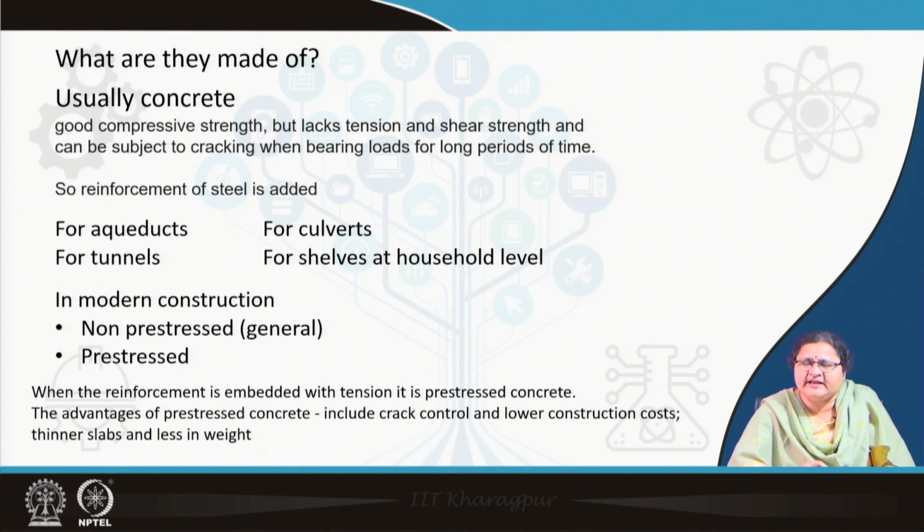In a precast system, you can pre-stress the rods and pour in the concrete. Then that becomes much more effective in taking strength and larger spans can be achieved. Thinner, lighter slabs can be achieved by pre-stressed mechanisms. Otherwise, you can always go for non-pre-stressed structures.